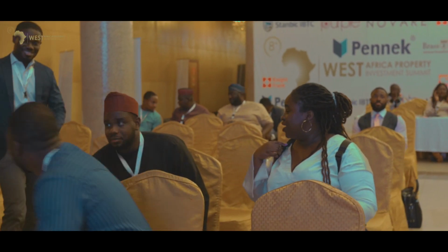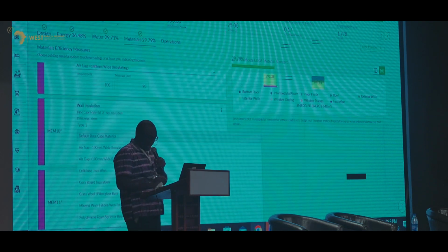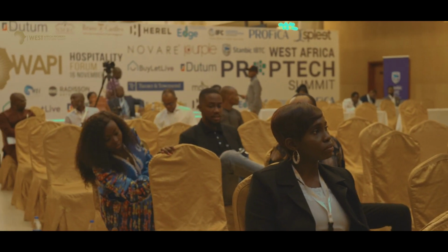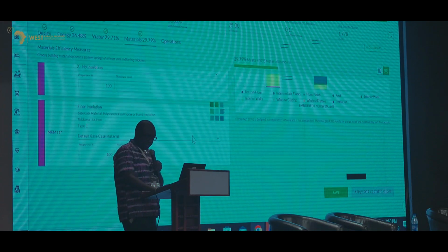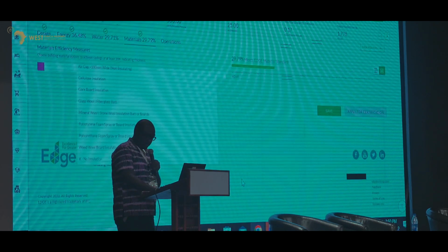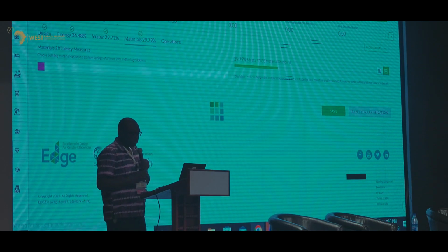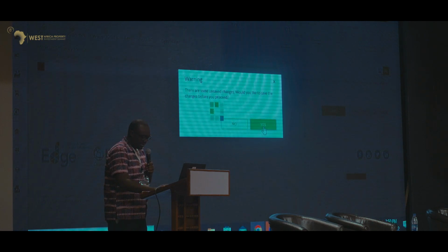Then the wall insulation, we don't have an external wall insulation, but because we are using hollow concrete blocks, the air gap also serves as some kind of insulation as well. Then for the floor slabs, no insulation.